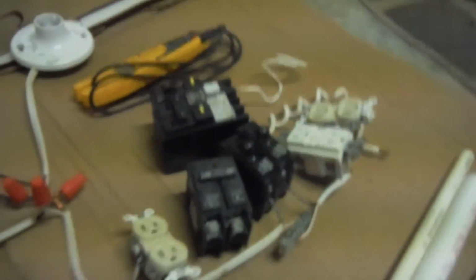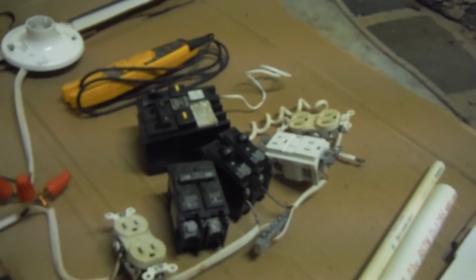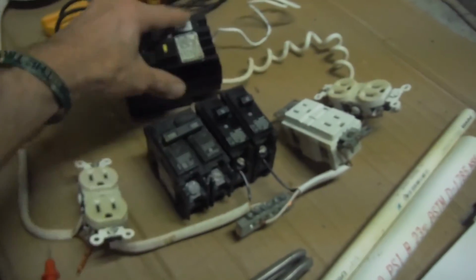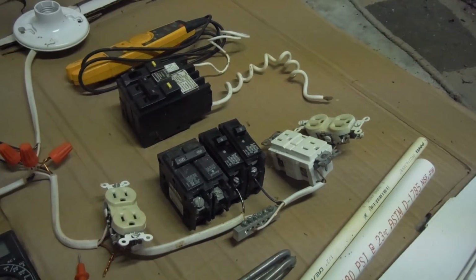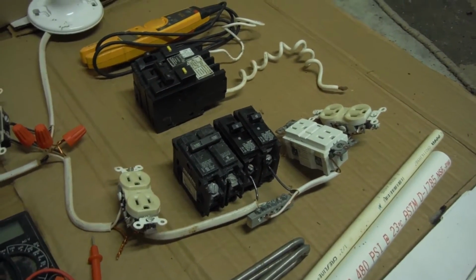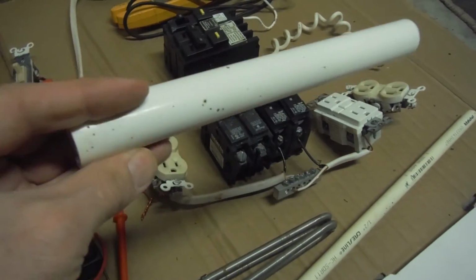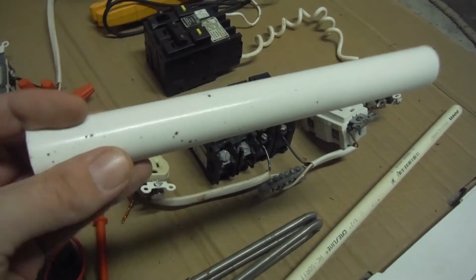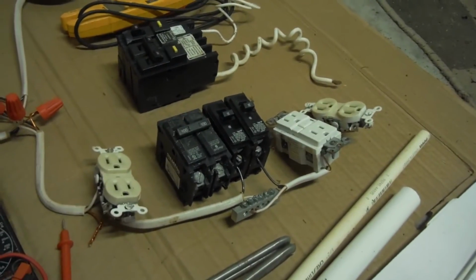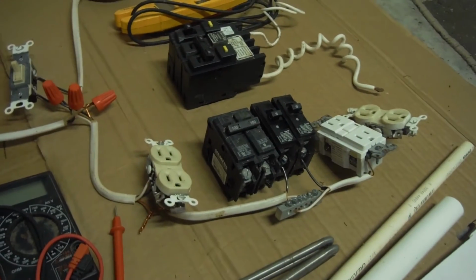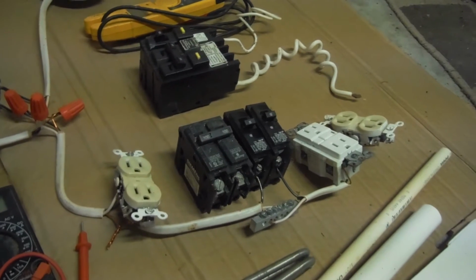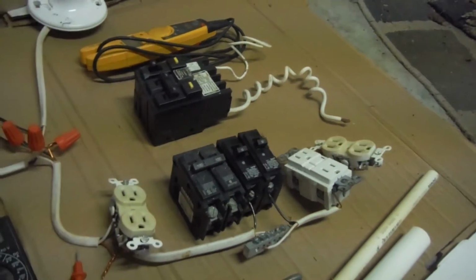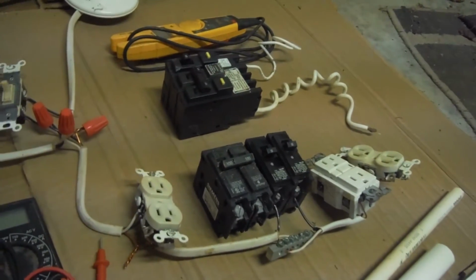And then it would be GFCI protected. And GFCI is ground fault circuit interrupter. And if you don't know about them, they're awesome. They are so great. They've saved my life many, many times. The way it's been described to me anyway, they measure the amount of amperage, which again, you've got your voltage, size of the pipe, amperage, how much water is going through the pipe, and resistance would be the resistance within the pipe. But it measures your amperage, and if it deviates, I forget what it is, 1/100th of an amp or something like that, it just trips itself. So pretty much it's detecting that there's going to be a short to, say, your hot tub where you're soaking in and you're going to get electrocuted. It just goes ahead and trips the breaker.